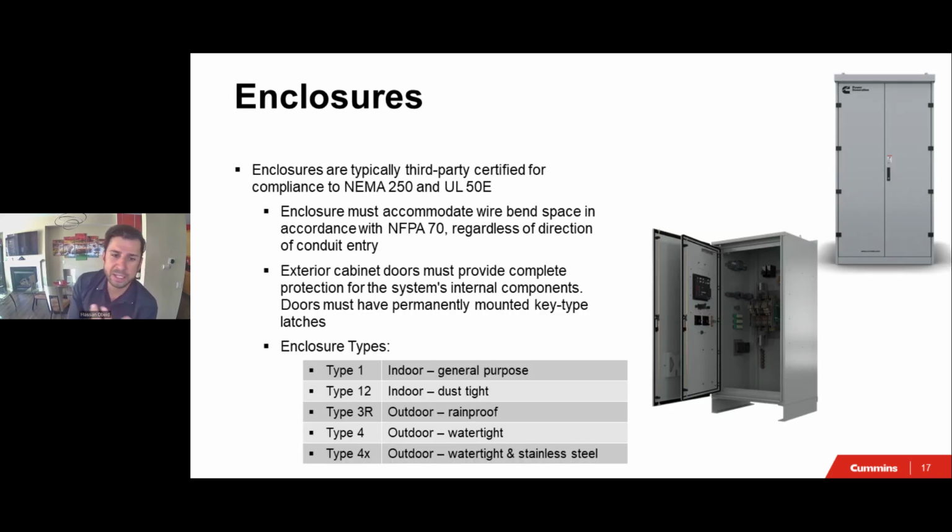Regarding the enclosure, obviously you can't have just a transfer switch out in the open. It needs to have some kind of an enclosure around it, right? And those are designed to meet certain standards, and the typical enclosure types depend on the environment where this is going to be installed, right? You have a type 1 and type 12 are for indoor. A lot of people think that a type 12 is the highest number. So yes, it has the best protection, but actually type 12 is an indoor application.